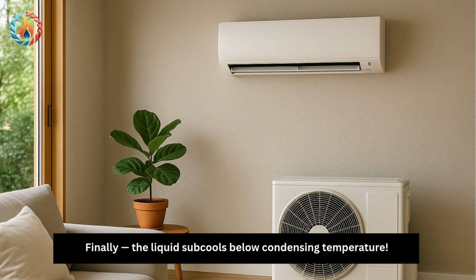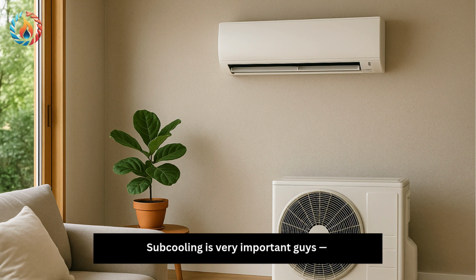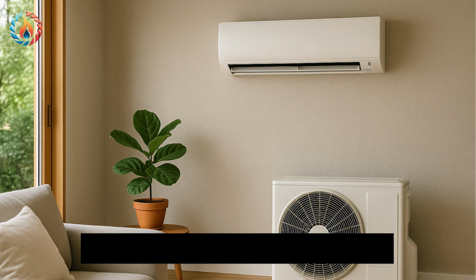Finally, the liquid subcools below condensing temperature. Subcooling is very important, guys. It ensures only liquid enters the expansion valve, no vapor bubbles. Vapor bubbles would reduce system efficiency. At the end of condensation, refrigerant is high-pressure, subcooled liquid. Stage 3. Expansion.